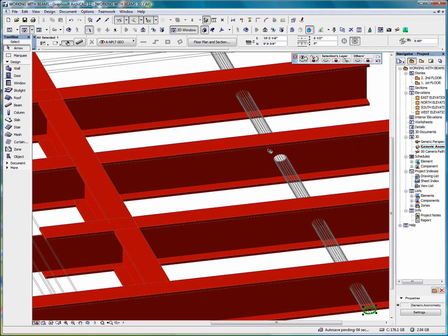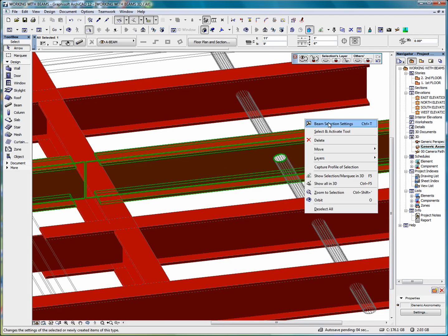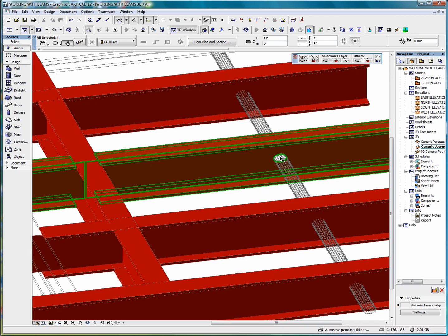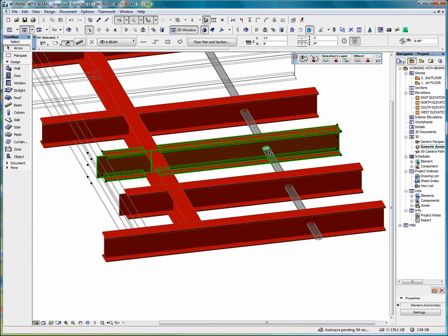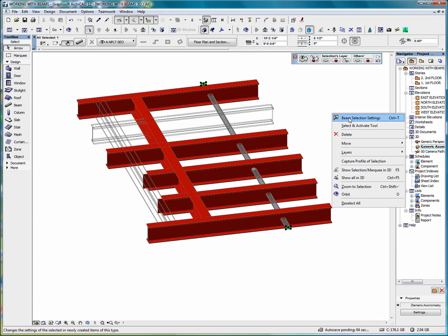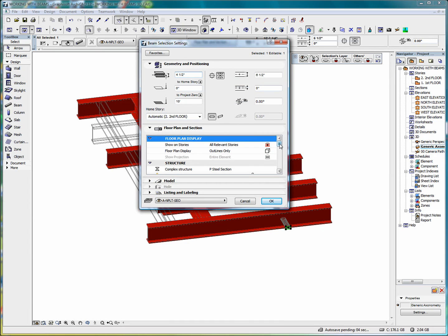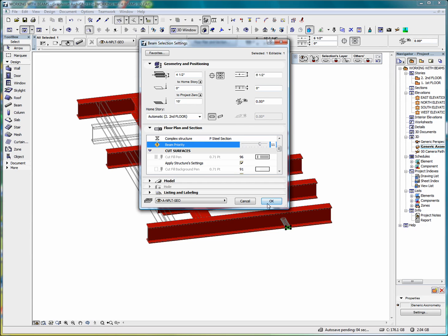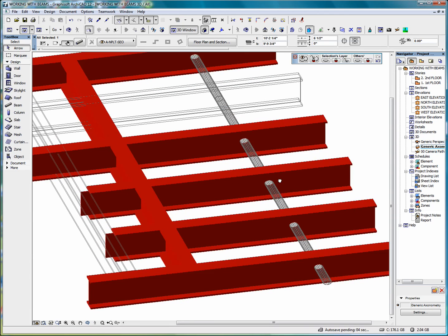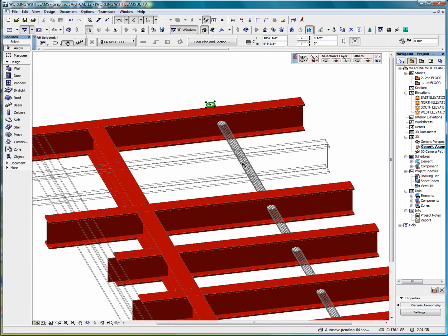As you can see, we can see daylight here, and the reason for that is we have set this beam at a priority of 5, and that allows this pipe to cut through that beam. Now if we were to select that pipe again, and bring that up to say an 11, now you can see that we've cut through all the beams.